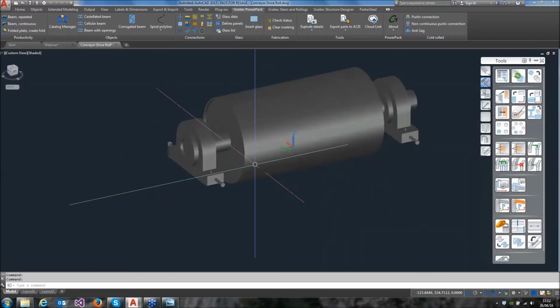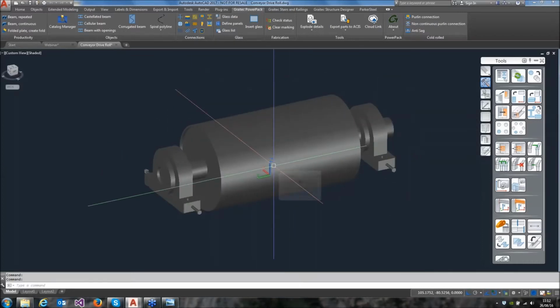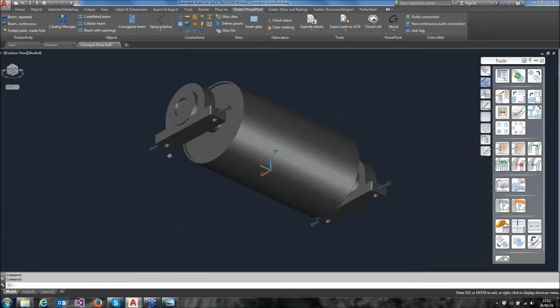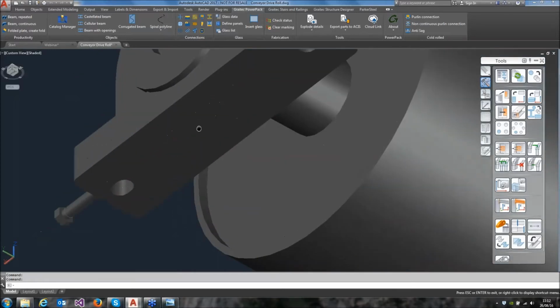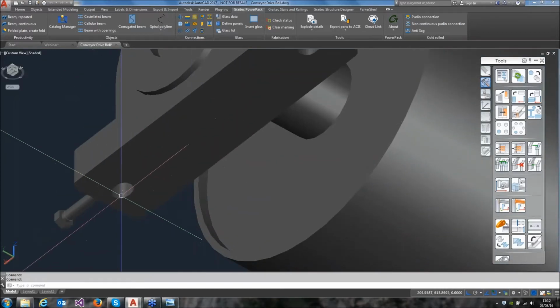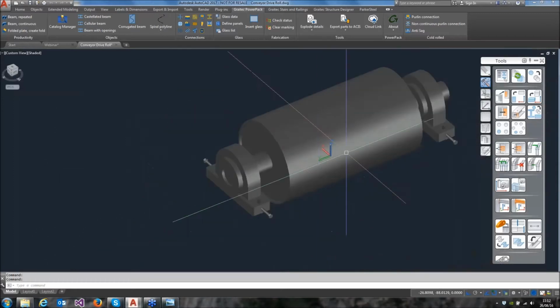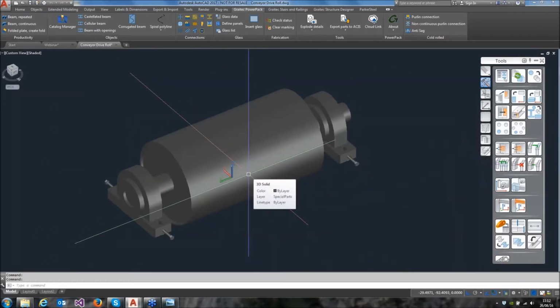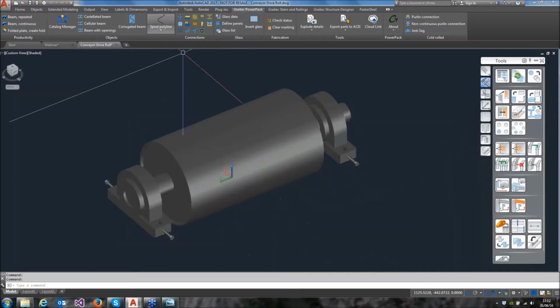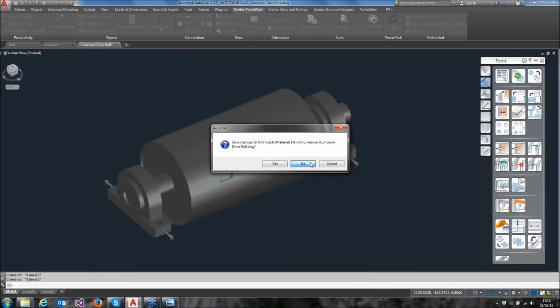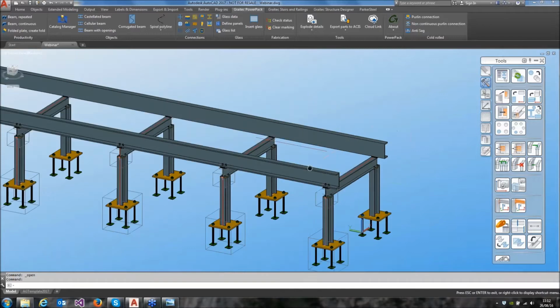Now what I've done in there, the 0 point needs to be, like using a block in AutoCAD, your insertion point. Everything else in the file is just 3D solids, no blocks, no other elements, no meshes or surfaces, just 3D solids. But I have also put in a couple of AutoCAD points. Can you see the white dot there and there? Hopefully you can. These are just point objects in AutoCAD. But those are points that are significant to the block, so I can use those to lock onto when I insert them into the main model.